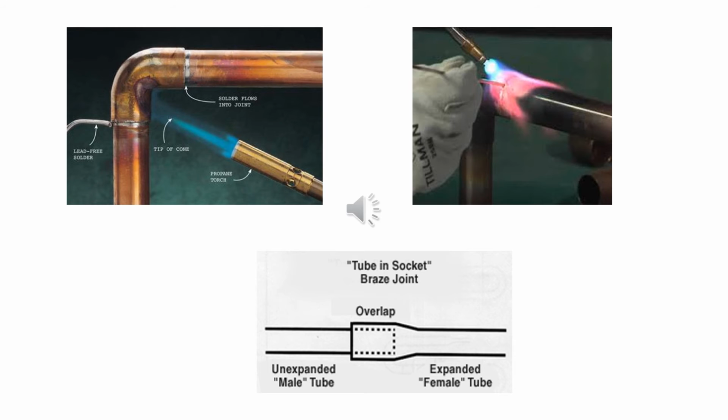The primary element used in solder filler metals is tin, because tin has an affinity for copper and wants to adhere to the copper tube and fitting. However, the use of pure tin would make a very weak joint. As with any pure metal, it would be difficult to work with.